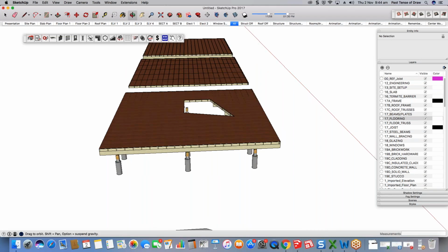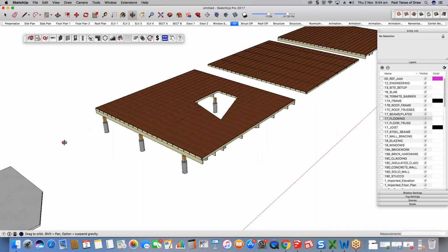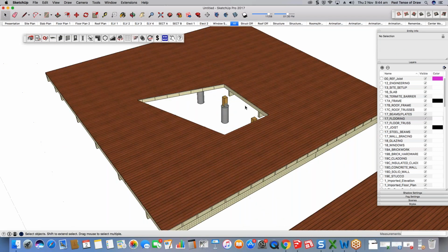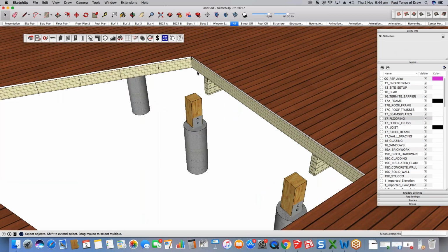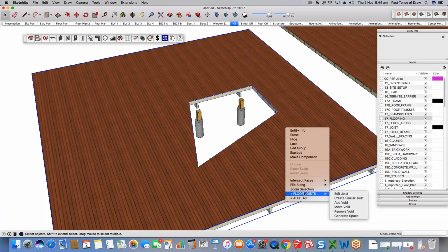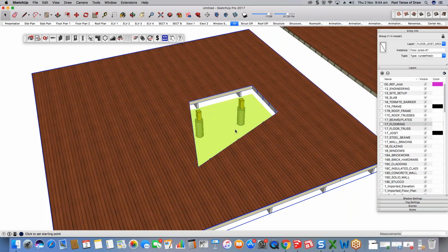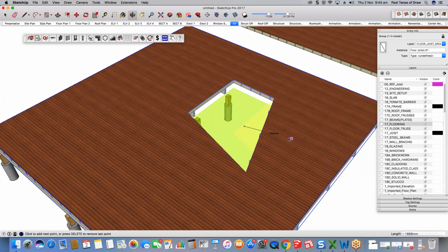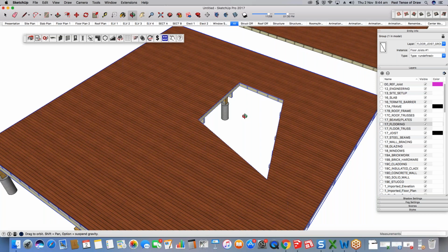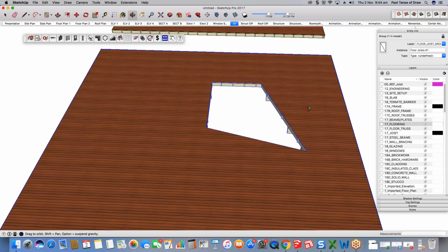Done. And one of the best parts with PlusSpec for SketchUp is that because you're using building components, you understand very quickly if there's a mistake and if things are not working. Now, the best part about using parametric tools like the floor joist and every single one of the PlusSpec tools is that if you do want to change things, typically they're done via a click of a button. So I'm going to select this shape that I made, I'm going to move it across this way, and now I've fixed my cut and it now works with what I need. So very quickly and easily updated.